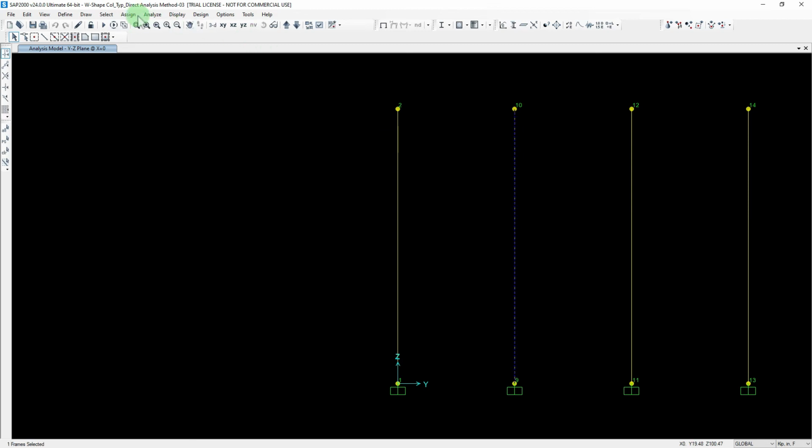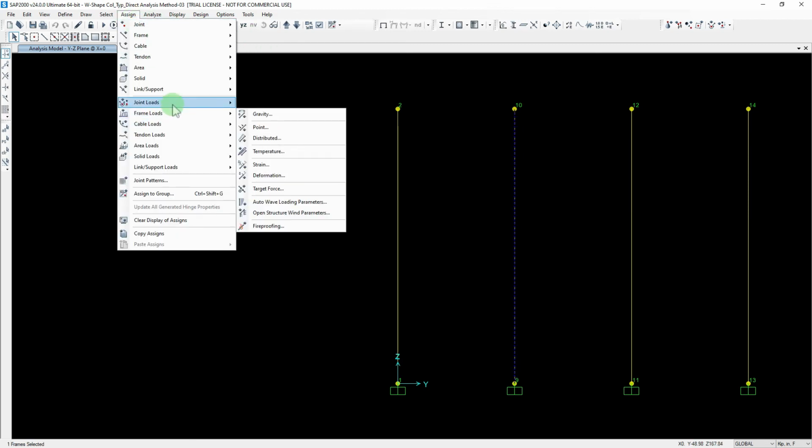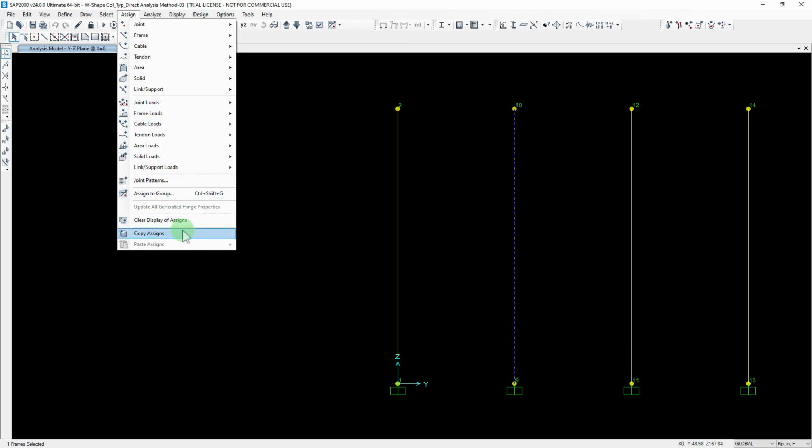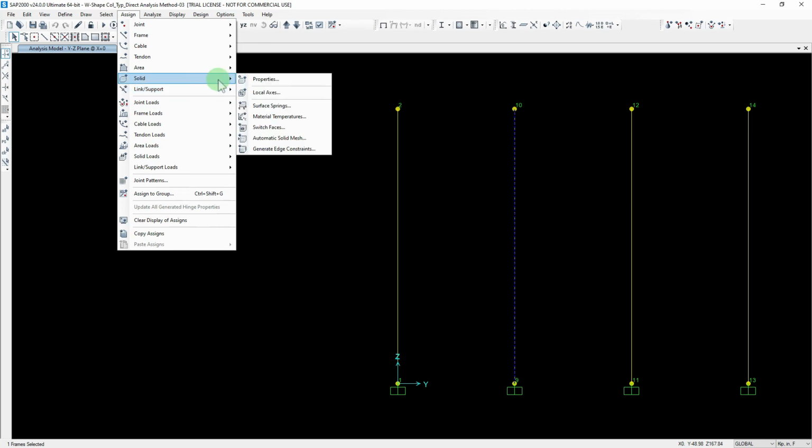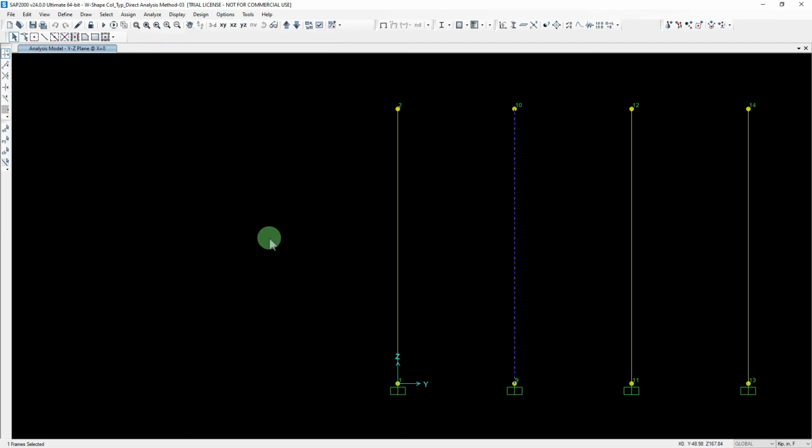I'm going to take this and add an intermediate load, right, internally, without breaking the member up into different pieces. If you break the member up into different pieces, that will also affect your analysis. You have to take a look at some other videos to view that, but that would affect the analysis because the computer would just basically think the member is going from node to node. That's a manual division of the elements. Here I want a kind of internal division of my elements. So this is the best way to do it.